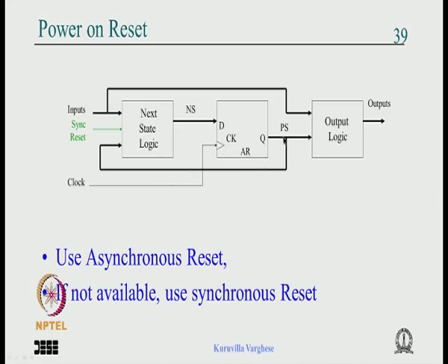So there could be 4 paths, Q1 Q0 D1 D0, 2 by 2 you have 4 paths. So you know that if you consider that the clock comes, there is a TCQ delay, there is a delay through the combination circuit, and that data has to be here setup time before. So the clock period should be greater than TCQ max plus T comp max plus T setup max, okay. And with the incomplete information we have, given a clock, the output appears here after TCQ and T output logic. So whichever is greater, we choose.